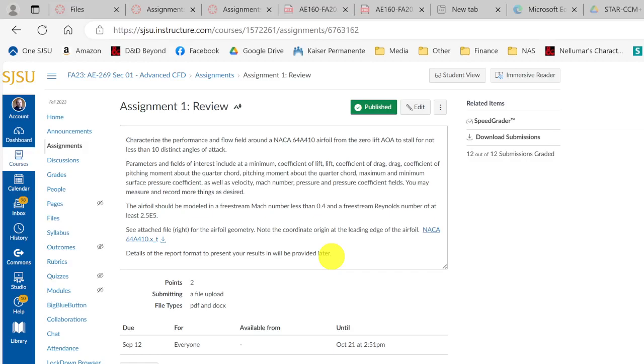I forget where it was exactly. I know the Mach number I set to the max of what you defined, and my Reynolds number was... I thought it was slightly above the minimum, but... Did you crank down the density? I don't think I did. Because at sea level, I'd expect 0.3 Mach to be way the hell above 500,000.